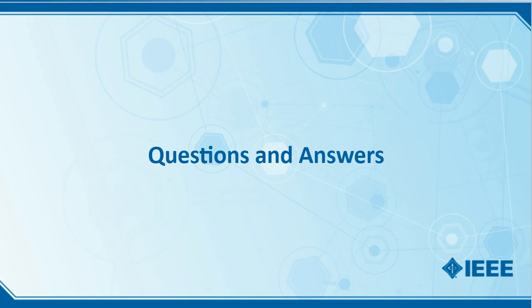Yeah, I can take that question. The control-oriented model is at the heart of our model-based controller, like model predictive control. It could be data-driven or physics-based, but eventually the parameters of this model should be tuned such that it is very close to the plant model, to the real vehicle model, with a 5%, 10% difference. Therefore, it should be accurate and at the same time very simple, because our MPC controller needs to do an optimization based on this model to find the best actuation. So it could be both physics-based or data-driven, as long as it's close to the real vehicle and computationally simple.